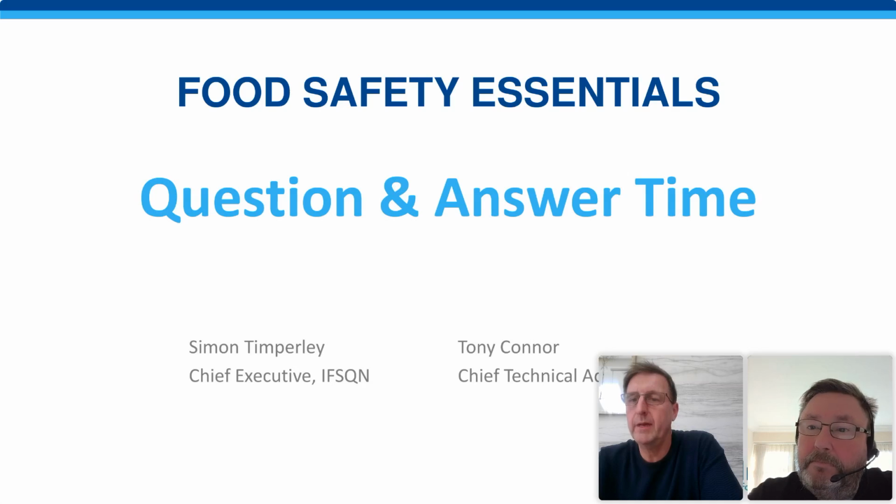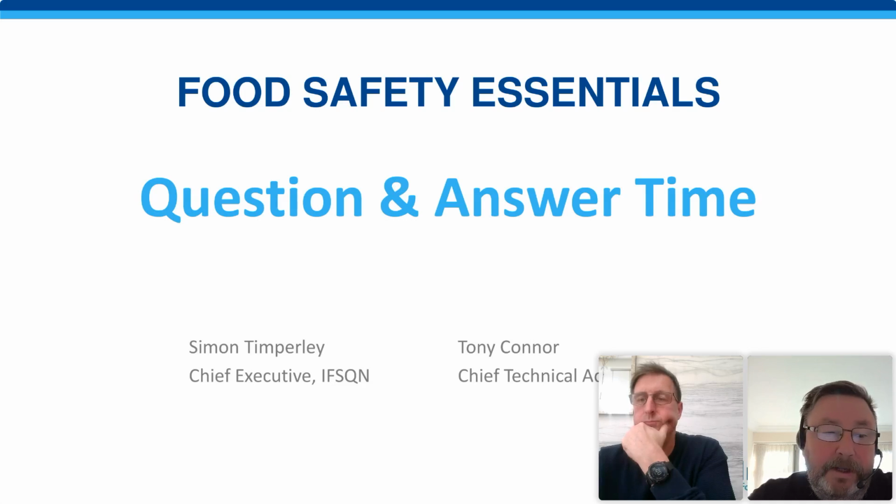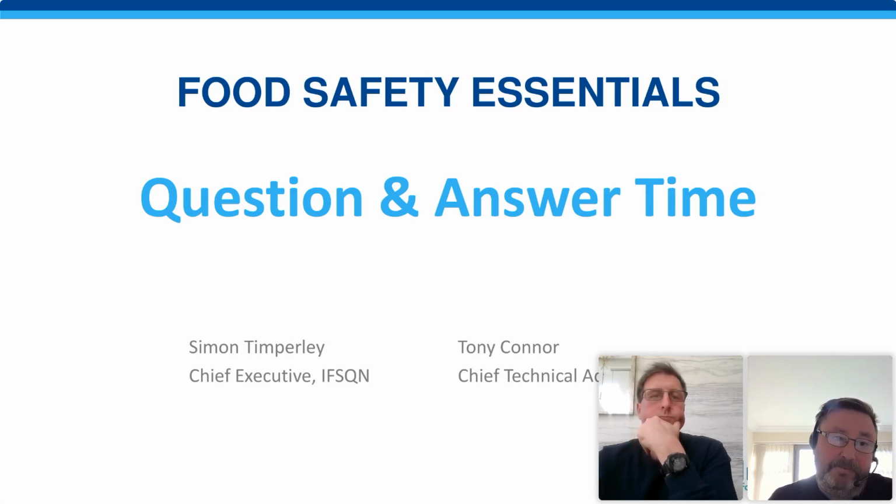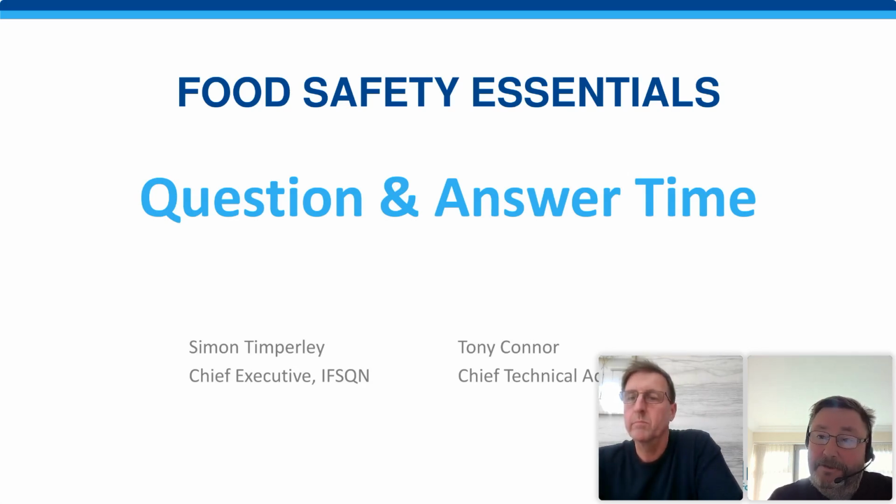Question from Dr. H.J. Shankaralinge. Hope I got that right. What is the best control measure for air pathogens in the food industry? It would depend on what the pathogen was and the application, but you can use irradiation, you can use hydrogen peroxide in machines, you can use UV light. When there's a problem and you need to protect the product from the air, usually you have filtration to a certain level. You might have a sterile air chamber in which the product is packaged. So it depends on the product, but ozone, peroxide, UV, could be irradiation, I guess. Filtration, yeah, HEPA filters. Okay.